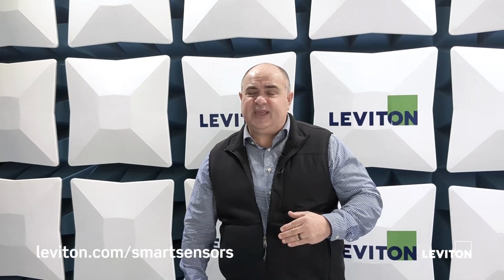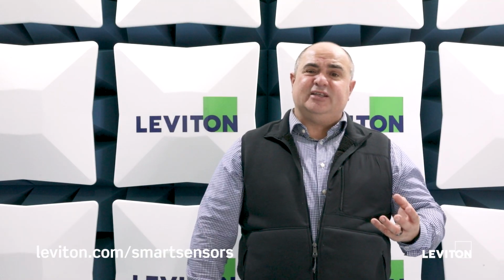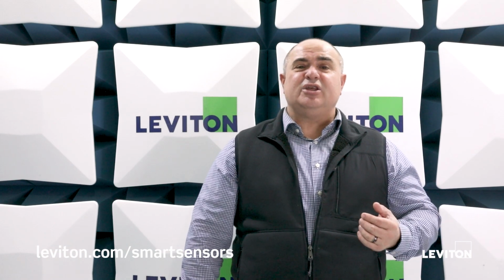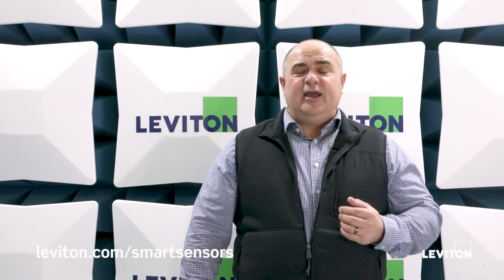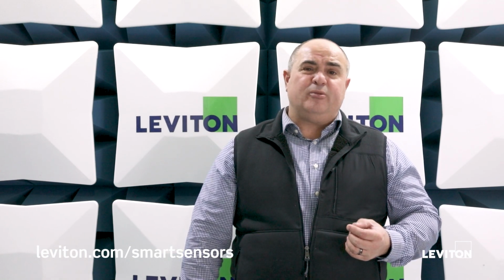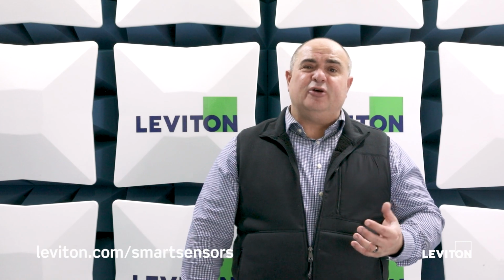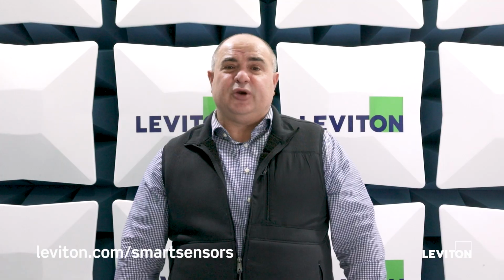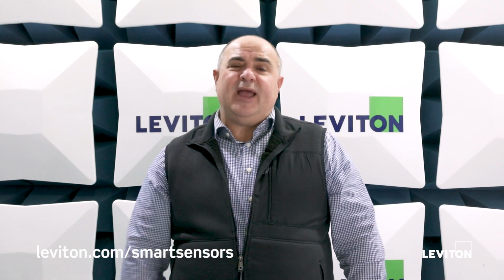When that room is vacated, the sensor then senses that the room is no longer occupied, and as such then turns the lights off. Okay, and there's a lot of opinions about that. A lot of people love the fact that they walk into the room and the lights turn on. Energy codes have looked at the idea of vacancy sensing as an opportunity to make sure that the lights are not turning on, that you don't have any false ons triggered, so you want that manual on.